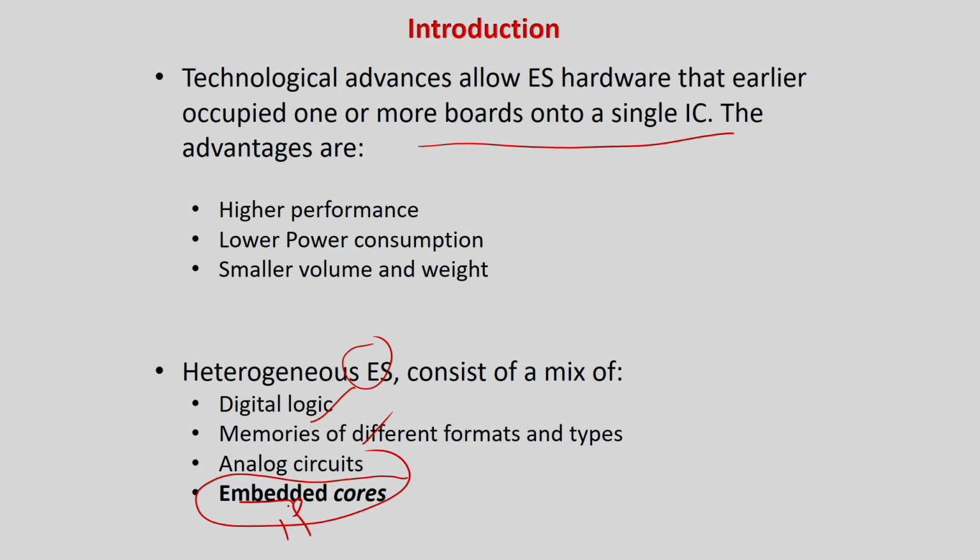But again, I want to say here that testing an IP core or testing that IC in isolation has no problems, and is very similar for test pattern generation. The test pattern will tell you what to apply and what you will get out as the golden response. Only when multiple cores are put on a single die, the main problem is in accessing the test points. That is the main challenge of core based testing, which we are going to look at.